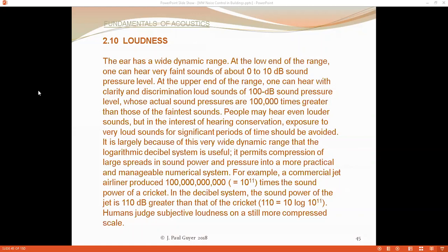If it was set on the fast setting, the needle would be bouncing around like crazy, and you couldn't read it in any meaningful way. So this knob, typically, you're going to set on the slow sampling rate. And now the needle on the sound level meter is readable. And you now read the meter, but again, that needle is still bouncing around quite a bit.